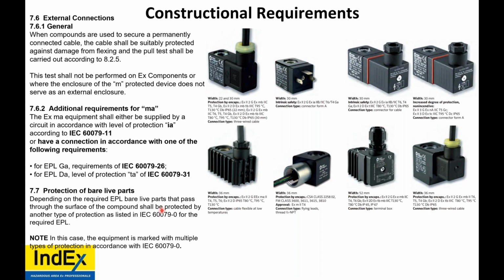Now, external connections. Where compounds are used to secure permanently the connection of a cable, the cable shall be suitably protected against damage from flexing and the pull test. That would be this bottom one here and this one here, and this one here. The test shall not be performed on Ex components or where the enclosure of the EX m does not serve as an external enclosure.